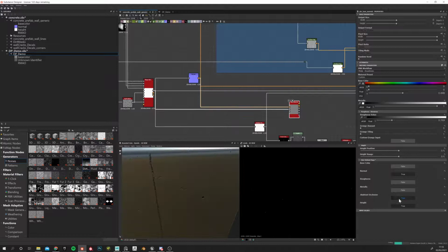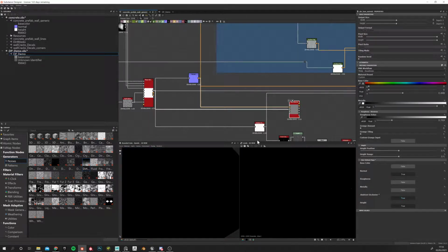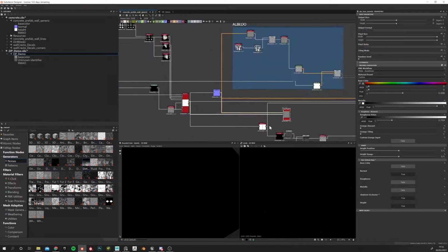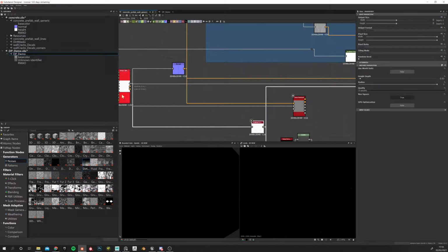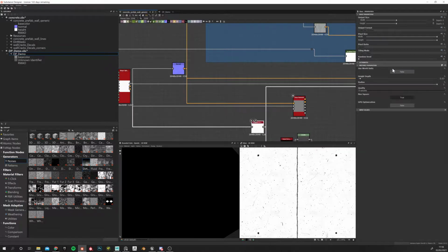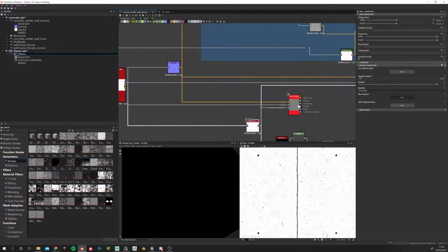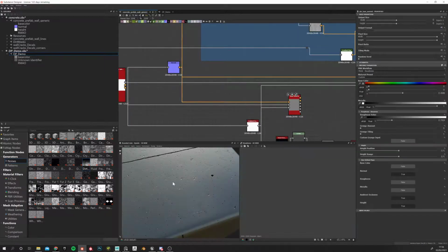No, not metallic, ambient occlusion. You can see everything goes black because it assumed there is nothing connected to it. So the ambient occlusion map takes the height map and gives me this, and you have to just tweak it. This is how much depth you want, the more depth, the darker you make it, and all that stuff. And if I connect it to this, then the shader will start looking with an ambient occlusion.